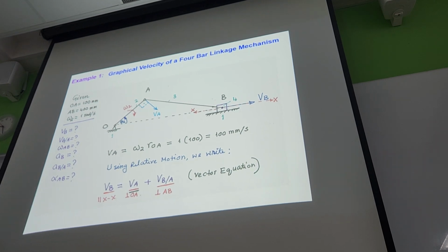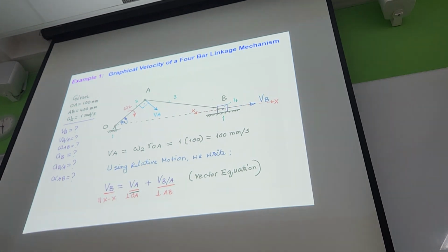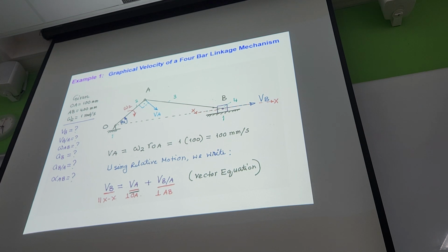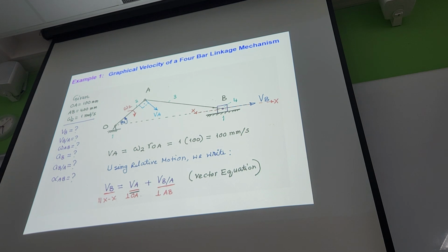That's the one thing. And then it says that links that have connection with ground, their velocities or accelerations should start from the origin of the vector polygon. Now let's have a look at our system. How many links have a connection with ground? We have moving links OA, AB, and our piston, correct? And now look here. Our OA, the crank, is connected or secured against the engine block. So the engine block is ground because the engine block is not moving, correct or not? So therefore it is our OA link that has a connection with ground.